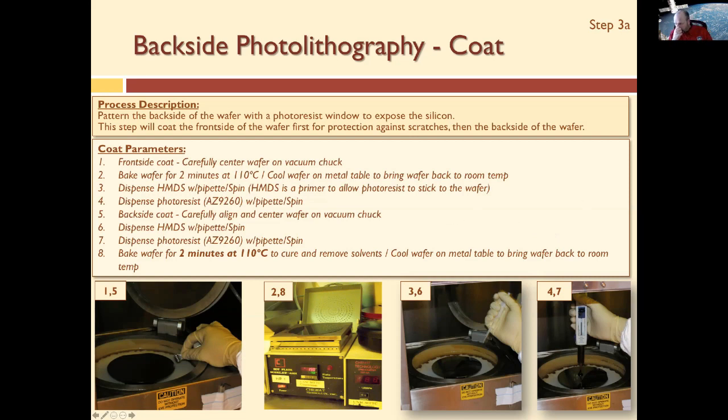Muriel has a question. Step 4 and 7, thickness of HMDS doesn't matter here. Remember, hexamethyl disilazane is a monolayer typically, so it's one molecule thick. So you can dispense it with liquid. You spin it on, and it'll evaporate, and one layer will remain on the wafer typically.